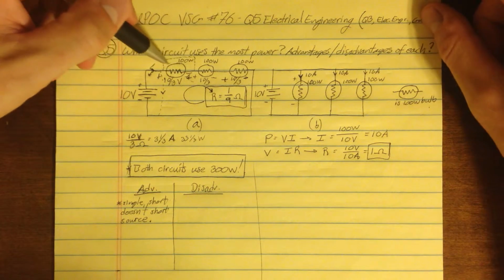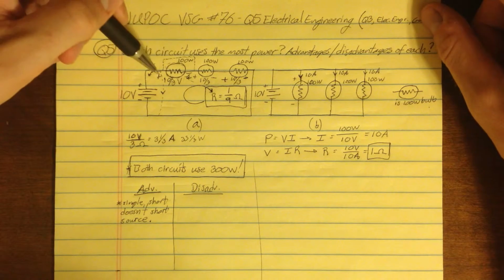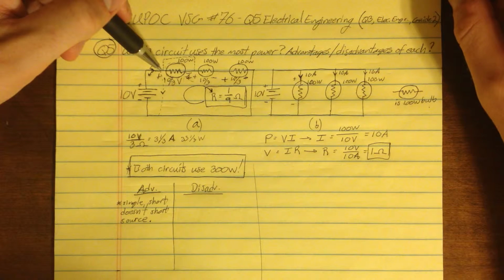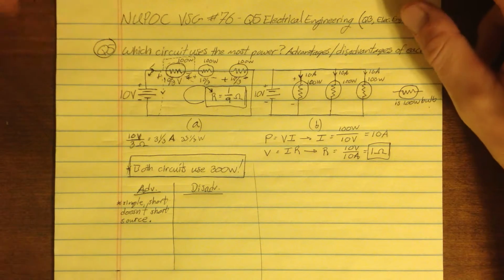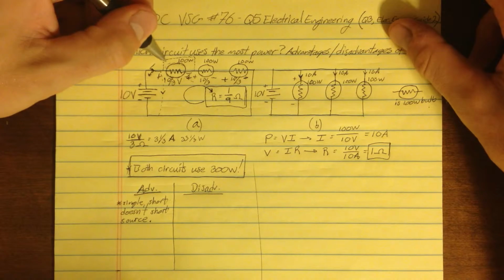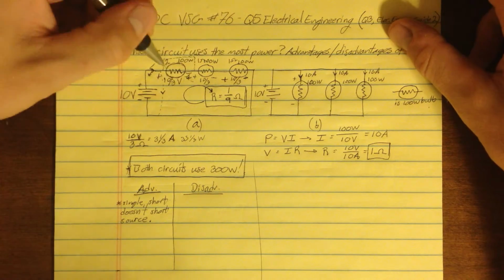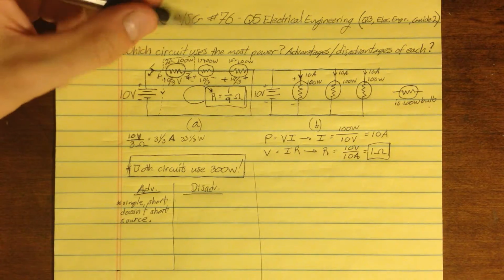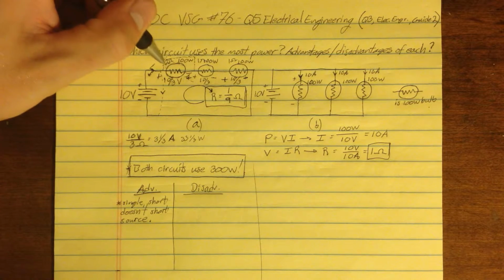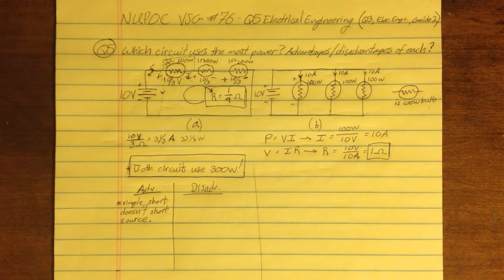But if this, for example, had a slightly higher impedance, then there would be more voltage drop across it. For example, if this was 2 ohms and this was 1 ohm and this was 1 ohm, the total is 4 ohms. But most of the voltage drop will come across this 2 ohm resistor, and you can use these two equations to see that.